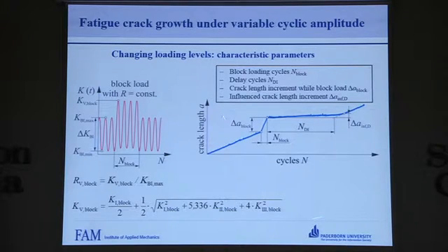On the right figure, a typical a-N curve of such a block loading test is shown with some characteristic variables which describe the retardation effect of such a low-high-low sequence.